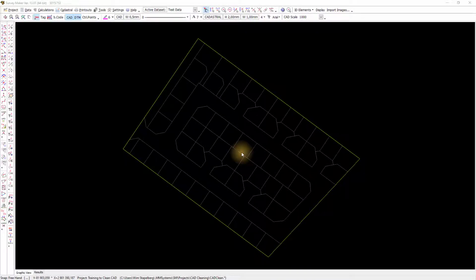The Fieldwork Line Running function will allow you to add new points with sequential names on your CAD layout, with various options to guide the process. The goal of the function is to greatly simplify setting out work in the field by creating the point names in a logical order. Select the function on the left points shortcut menu.